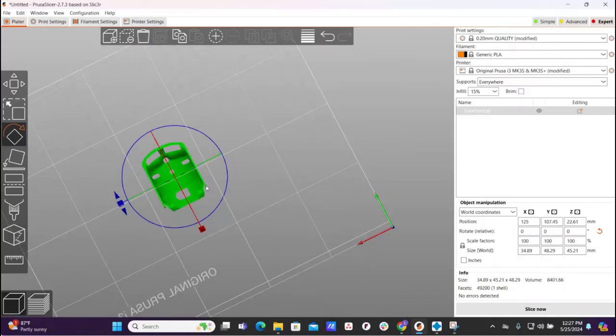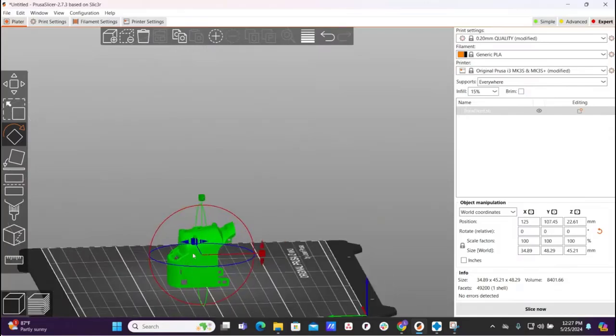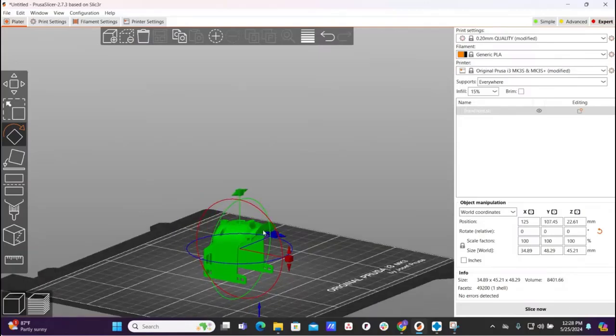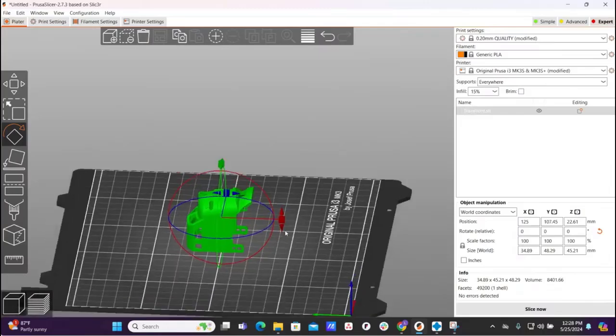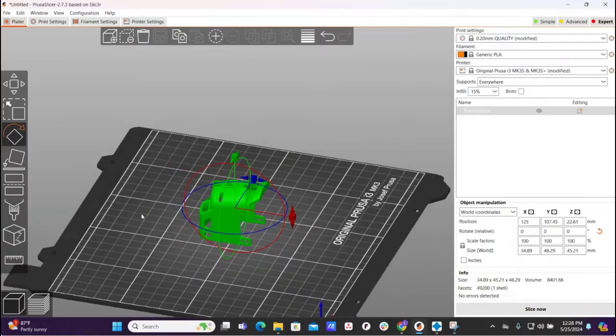And there are settings like brims and things that you can add to kind of hold this U shape down. But when we look from the side, everything stacks nicely on top of that U shape, versus this little piece here, where nothing stacked on it. Everything went out kind of like a lever, which would potentially make the print, as it got heavy and away from the place that's actually on the build plate, possibly delaminate, or one of the layer lines separate, or something that you don't want.